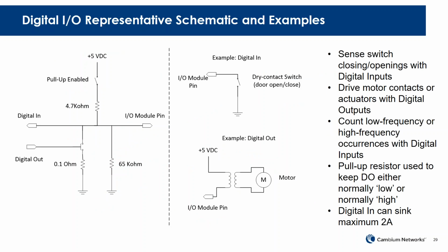Another capability of the product is it supports built-in general purpose IO. Some customers have deployed the product with sensors and dry contact switches directly connected, controlling devices directly off the radio. So in cases where I have simple needs or some small application for digital IO or analog IO, I can eliminate an external PLC or RTU and go directly to using that general purpose IO that's built in.